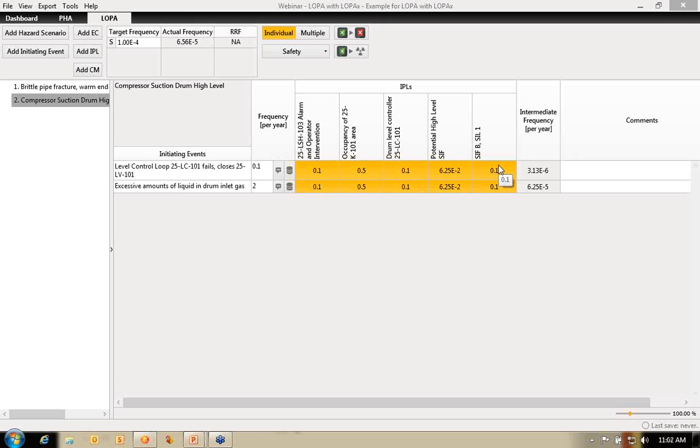You just say, hey, this is the SIF, this is the required risk reduction, therefore this is the SIL level, and it's not really that exciting. There are some customers that use a risk matrix or a risk graph to do their SIL selection, and in those cases, the initiating event frequency out of the LOPA is an input into their diagram. So in that case, you kind of need a separate tool to handle that. But absolutely, the key information, frequency of the initiating event, comes out of the layer of protection analysis tool.